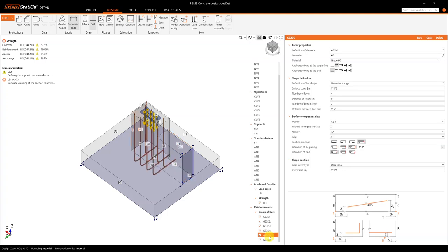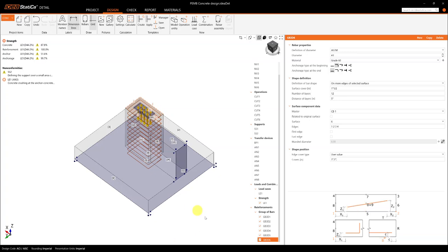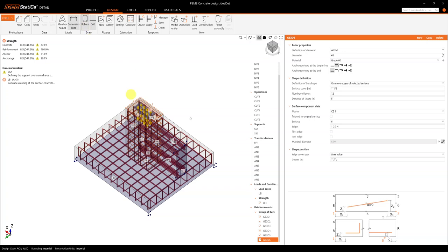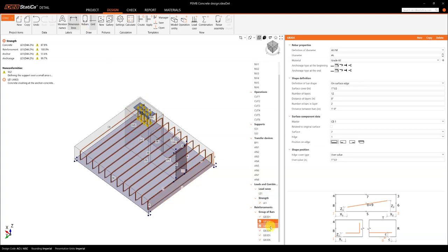Okay. Now I created this vertical reinforcement for the pedestal. And finally, I created the stirrups for this pedestal. So again, you will have the model. You can review it and see how I modeled this. Right now, I turned off the rebars here, but you can activate them and see them all at the same time. If you deactivate this, then you can navigate through these different rebars.